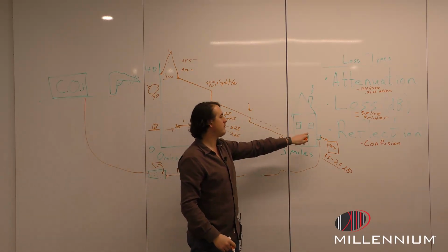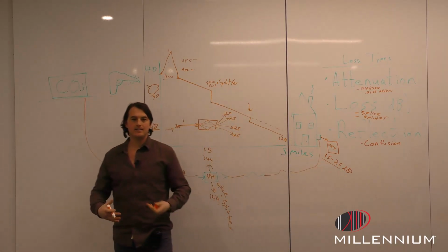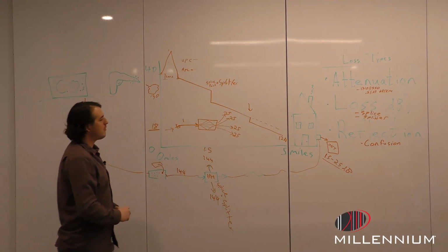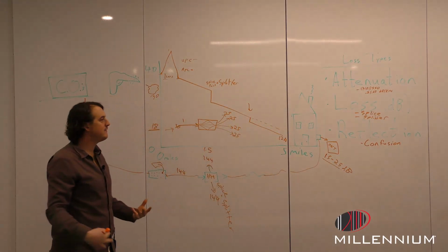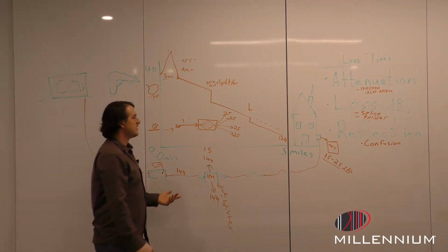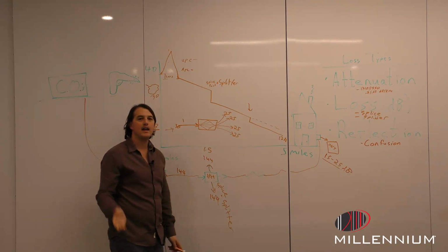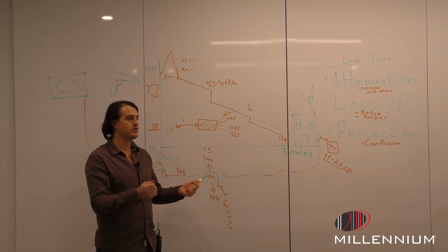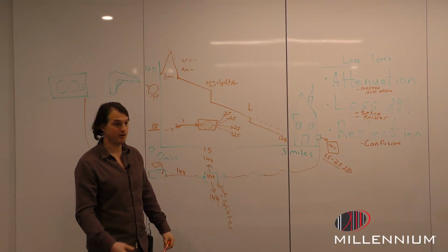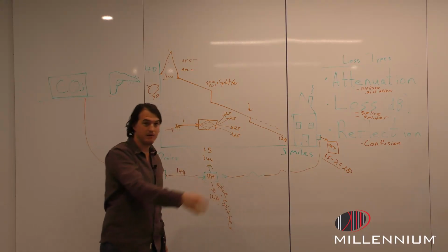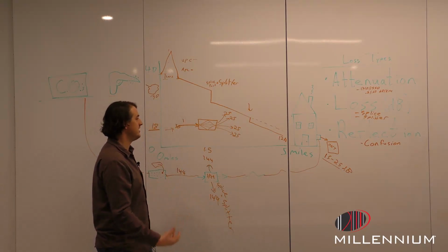Huh. Well, that is probably the reason why this customer is unhappy, because we're out of their ONT's range of acceptable light. Well, what the heck? 1310 went flying through here and said it was fine, but 1550 isn't working. It's a bend in the cable. Because 1310 is that hyper light, it can go through tighter micro or macro bends than 1550 could. 1310 is that El Camino, it can make a U-turn really easy. 1550, long bed pickup truck, not quite as much ease turning around.